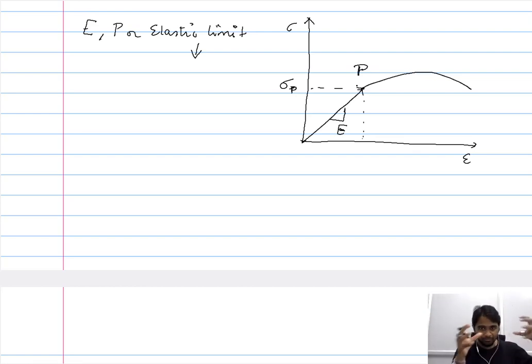So you have, in the polycrystalline material, already some amount of dislocations that are present, and when you impose the stress, these dislocations begin to move and they ultimately contribute to the plastic deformation. Now the elastic limit, or you can say the true elastic limit, is the maximum stress below which there is not much discernible movement of the dislocation.